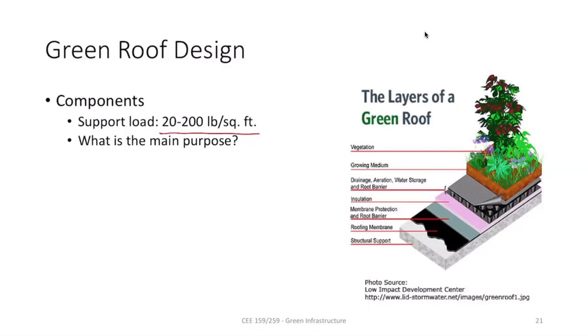are lighter. And the main purpose of a green roof is to allow water to drain. So drainage of water, mostly slow down the drainage, and store water. And the second is energy, cooling or heating. If you are heating inside, then that energy should not dissipate to the sky. So that's the second benefit of the green roof.